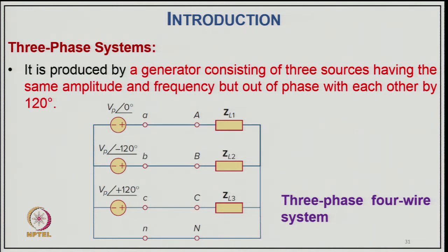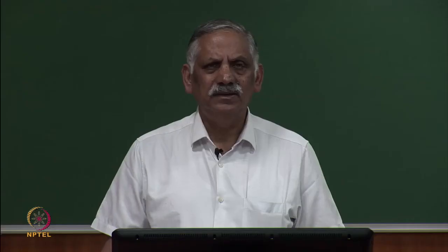Single phase load is provided with each phase connecting to the neutral, I mean the two neutrals together, the supply neutral or generator neutral with the load neutral. That we call a 3 phase 4 wire system. And we have to make such a polyphase system which can supply not only the typically large 3 phase load, but we should be able to supply a single phase load.